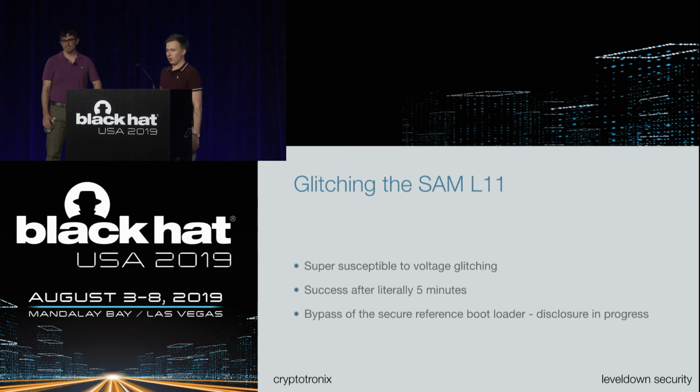It's a secure chip, and what's an issue for us is that we have customers coming to us who want to use this chip as an HSM, a hardware security module, besides their main chip because it touts so many security features, but once you start looking at it, it gets really, really easy to bypass. For example, we found a bypass of the secure reference bootloader, which runs in TrustZone and allows you to write a validated firmware. The disclosure of that is in progress. We hope to be able to release it soon.